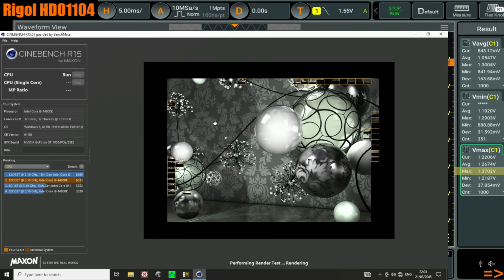This is the main issue I have with recommending undervolting to people: you are offsetting the operating voltage for every single possible combination of software and operating frequency on your CPU. And it is incredibly hard to test every possible scenario that your CPU is going to experience. That's why the CPU comes with such a massive safety margin from the factory, right?